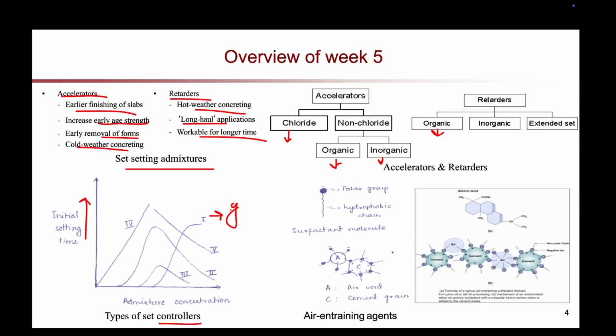So in that case, we are adding some air entraining agents. What air entraining agents will do is create a gap or a bubble inside the concrete. So whenever water enters those bubbles, it will expand and melt in that bubble itself, so it won't create any extra pressure on our concrete surface. So those are the air entraining agents.